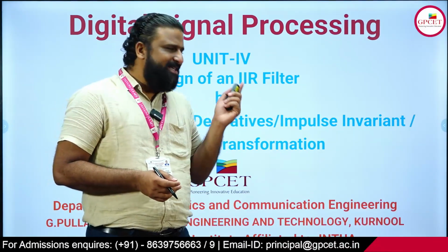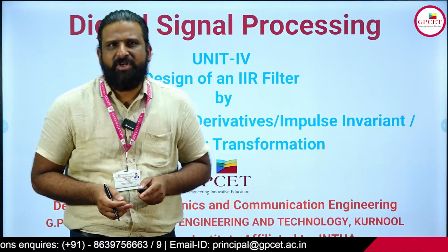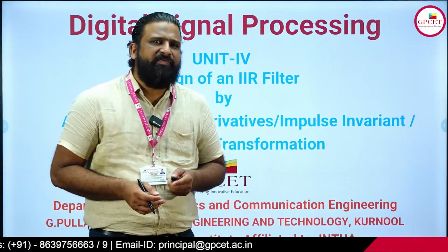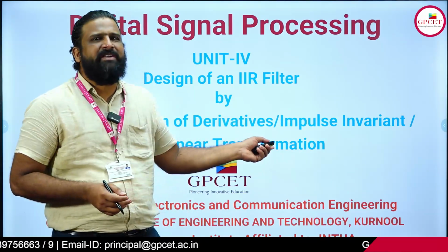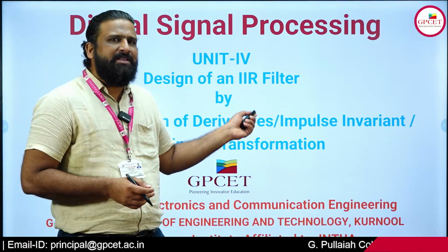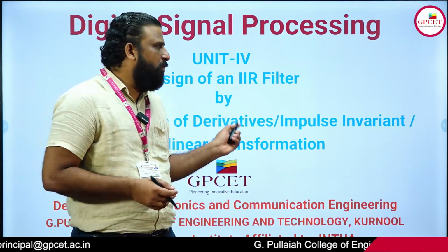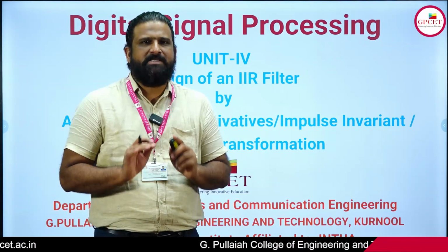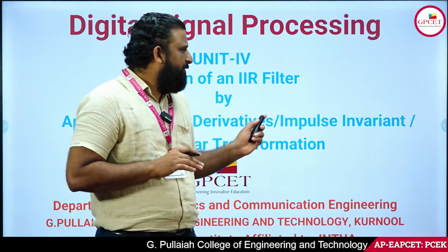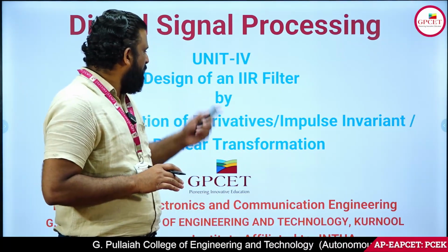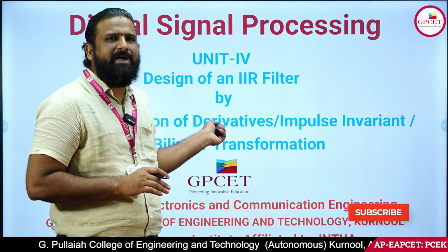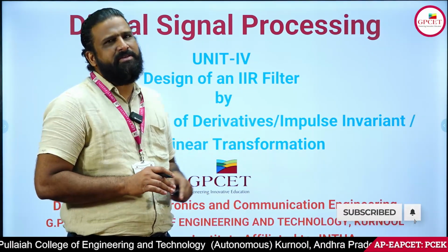After designing that H of S transfer function of analog filters, by using these three different techniques, it is converted into digital filters. This is the concept. Now we will see the steps involved in converting the analog filters into digital filters.